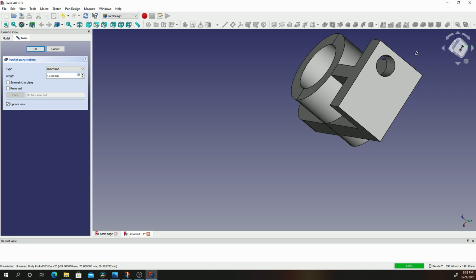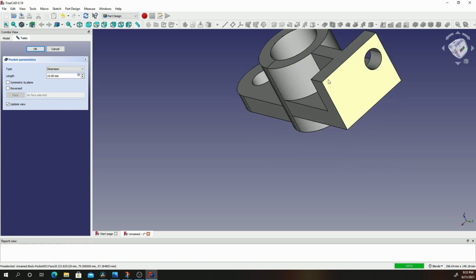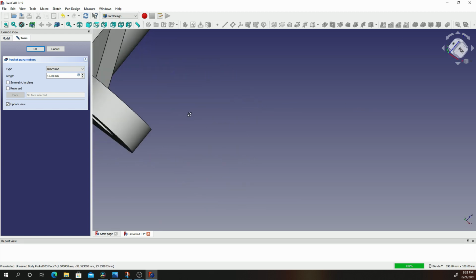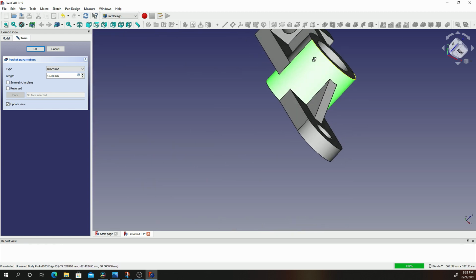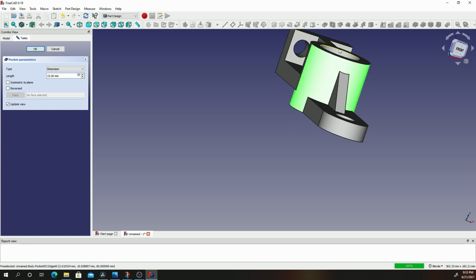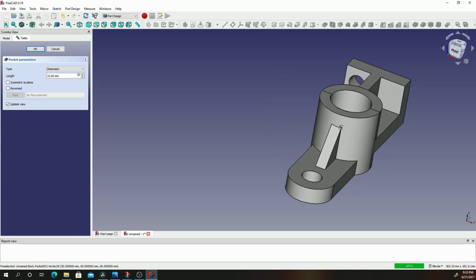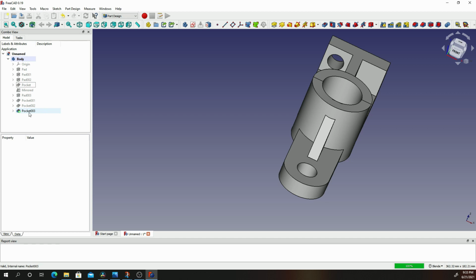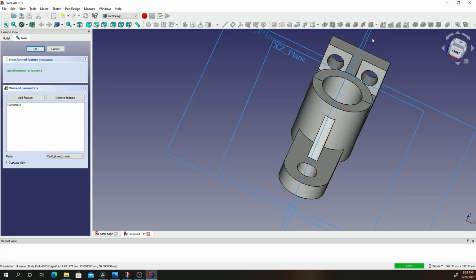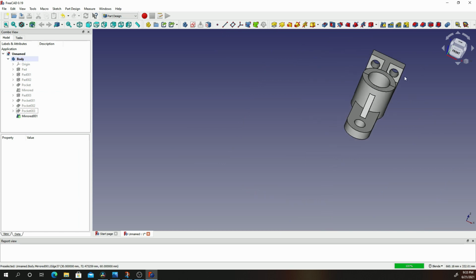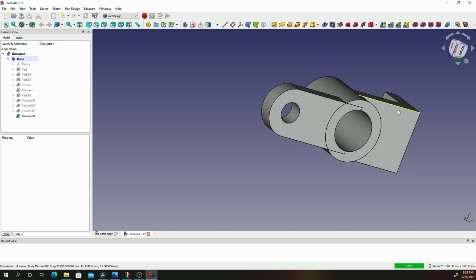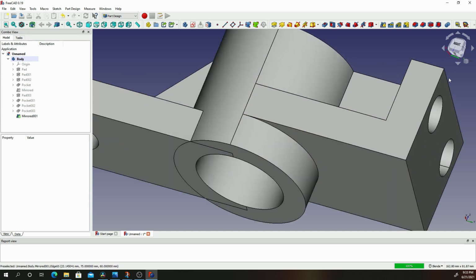So that will punch in only this dimension. It won't go through to the circle. So if you look at this, let me bring it this side. Let me bring it in view. So you can see we have the hole through there. So let's rotate it and we see. So once we're done with that, go ahead and click on OK, and then select that pocket and click on mirror, and then click on OK. Okay. And with that, we have our second mechanical joint completed.